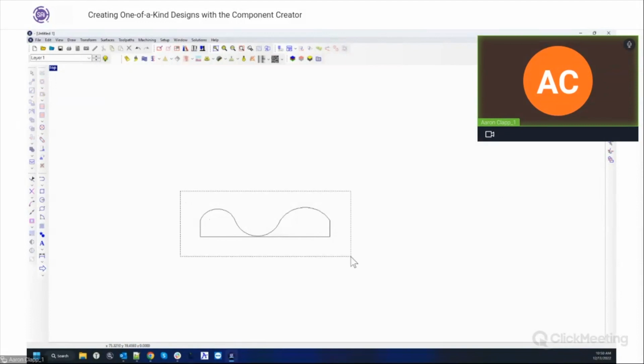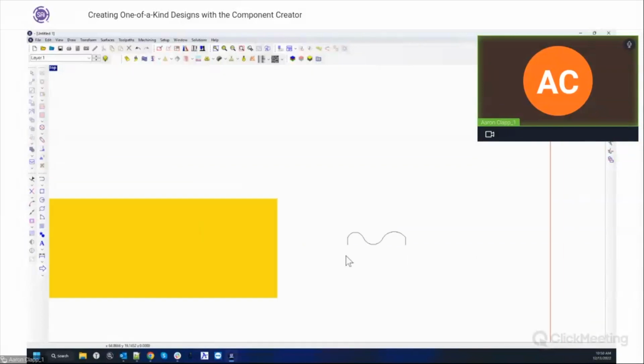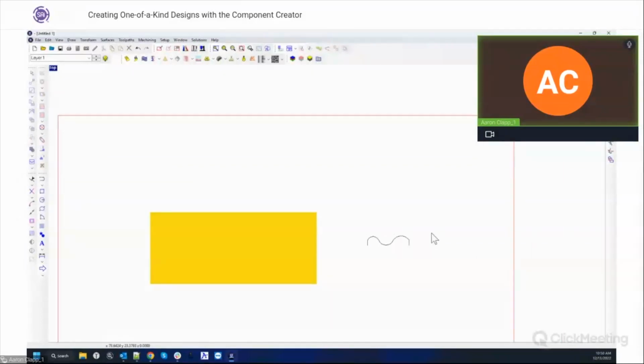All right, so now we've got our shape. We don't need this line. We just need those, make sure that those are straight. And I want them to be perfectly the same. The reason why I drew that line down there is I want them to be at the same exact height. I don't want them to be mismatched in height, otherwise that'll cause some problems. So we will merge it together so that it's one piece, profile. I told you I'd remember the word eventually. Profile. This is our profile.